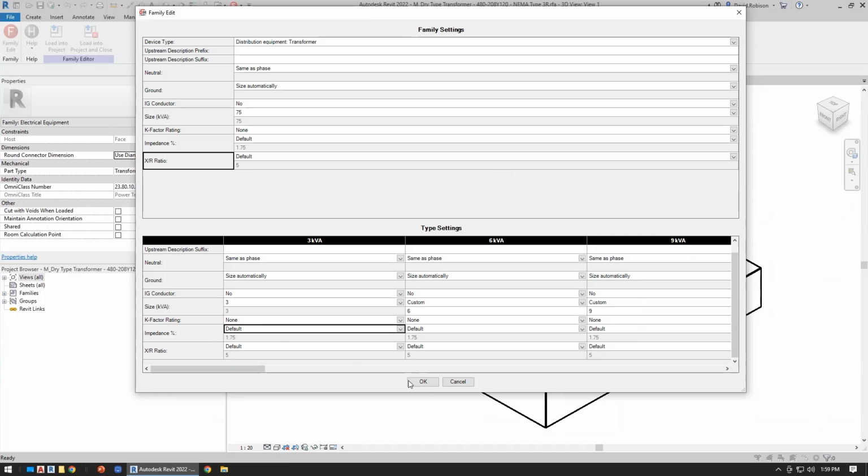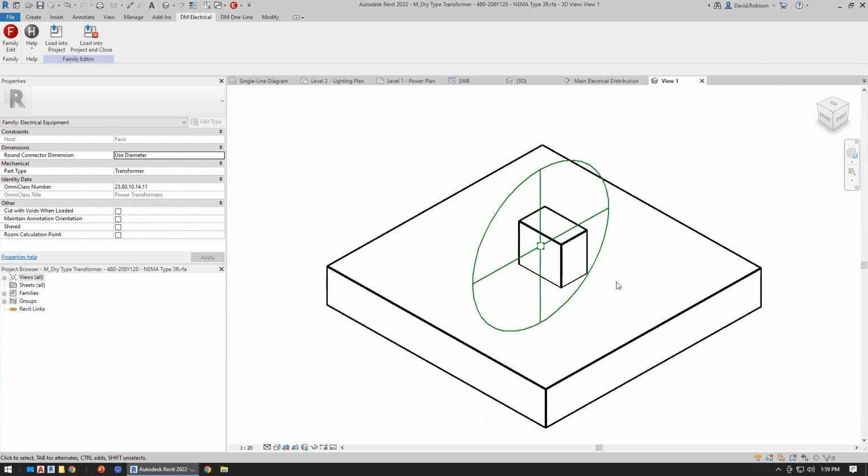And then that'll feed into the rest of our calcs. And that is how the family edit command works. The idea is that you can take your families and add a little bit of additional information to them, so that it's getting loaded up in your projects automatically without you having to make that change in every single instance in the project.